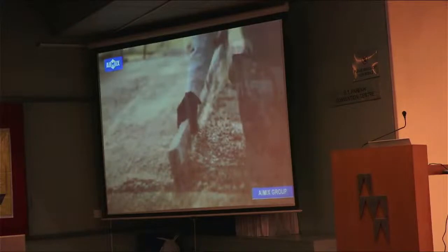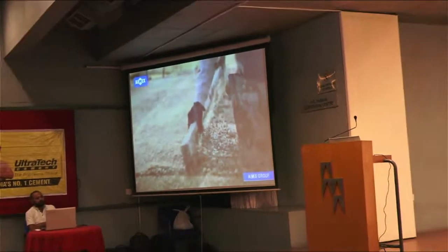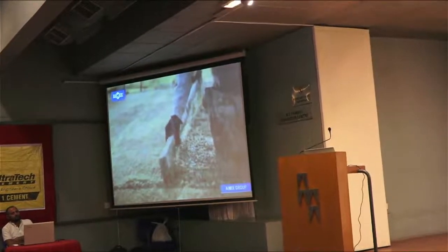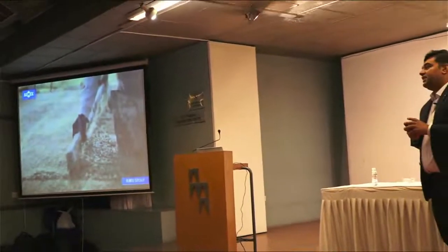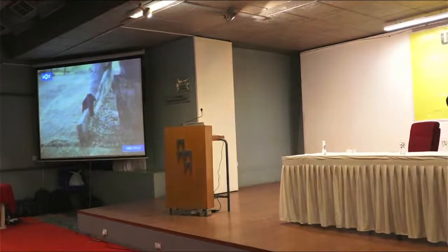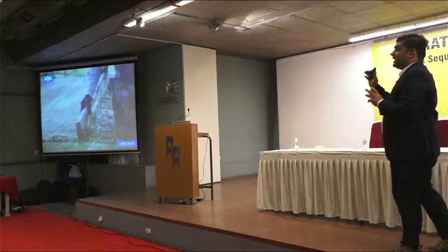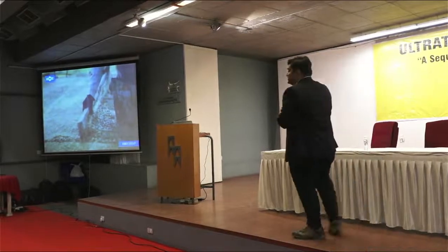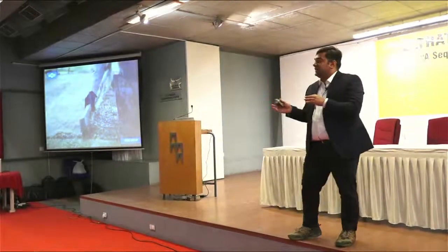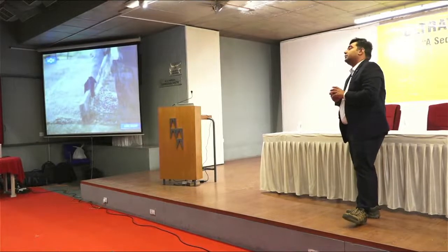Okay, so this was the video showing various types of modern RMC plants. Generally, these stationary RMC plants are placed at precast units where they require a larger quantity of concrete. Their capacity ranges from 60 cubic meters to 205 cubic meters per hour. The next are the mobile plants. The mobile plants are generally placed by companies at sites where they can be moved from one place to another, and the capacity ranges from around 30 cubic meters to 120 cubic meters per hour.